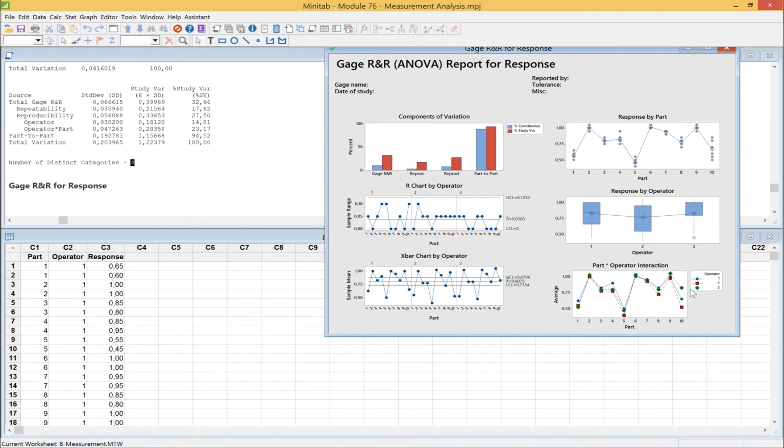So now, in the control phase, we want to go back and study why is there so much of a problem measuring part 10 for the operators? Why are the operators not as consistent across there? So is there a training issue that we have to fix in the procedure? Is there a problem in terms of the fixtures that we use for the measurement? Maybe we're not inserting part 10, or it's being inserted differently because of the geometry of the part. So what is actually going on?